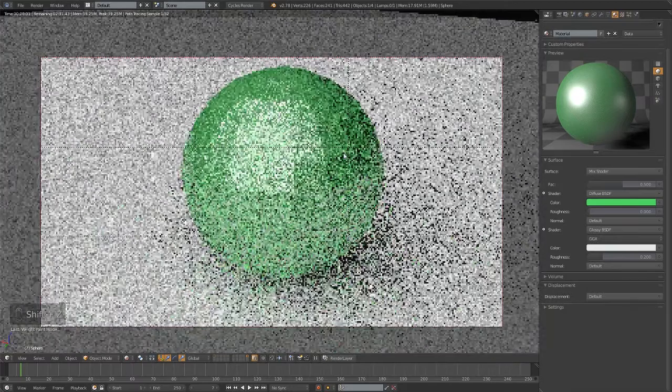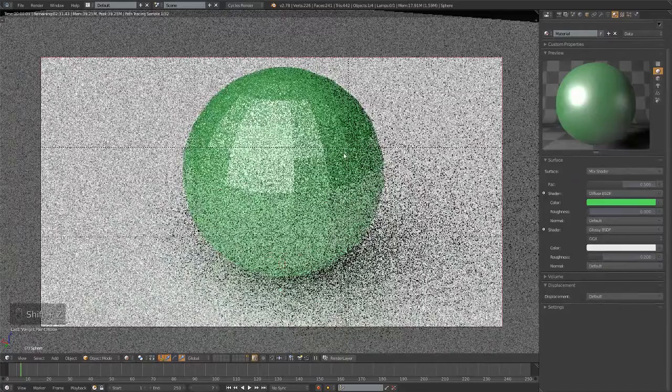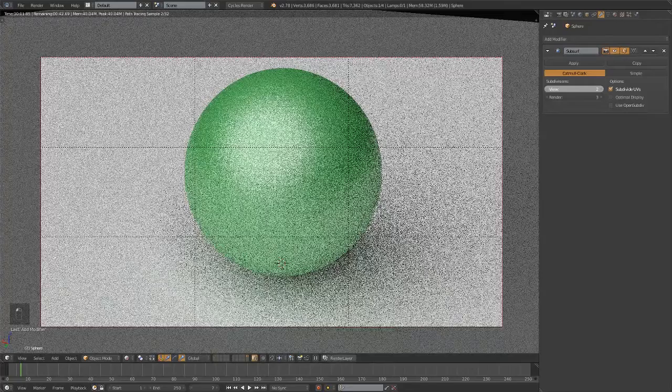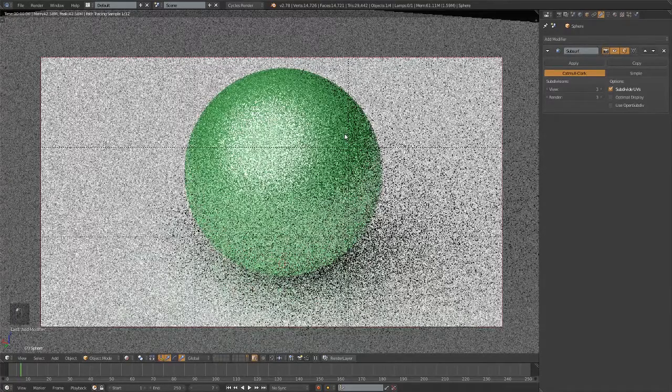Now guys, I will preview this. As you can see, there are a little bit of bending issues. For that, go to the wrench icon. This is called the modifiers tab. Add modifier subdivision surface. Choose both view and render values to 3. Then press T and just press smooth. Oh yeah. Now guys, this part I will skip a little bit, I will fast forward because this is not your work right now.